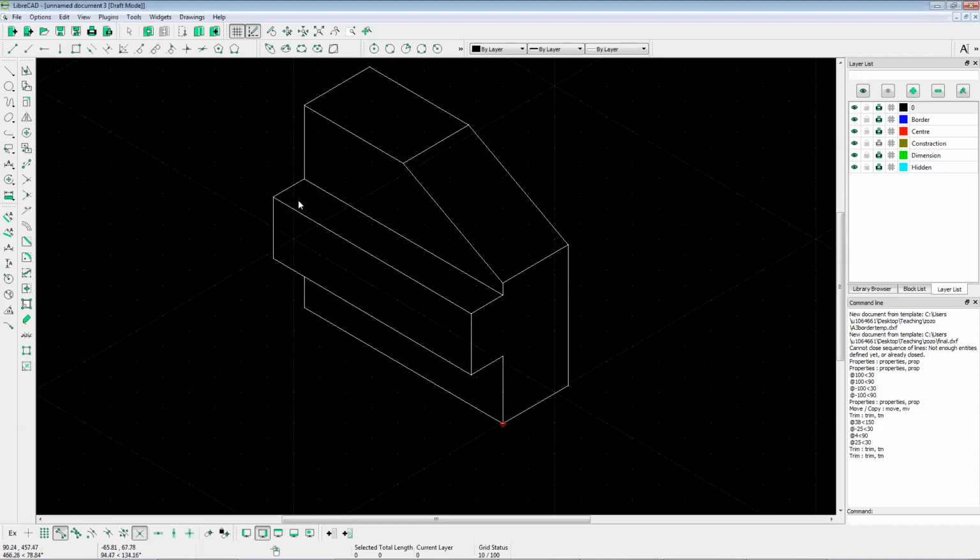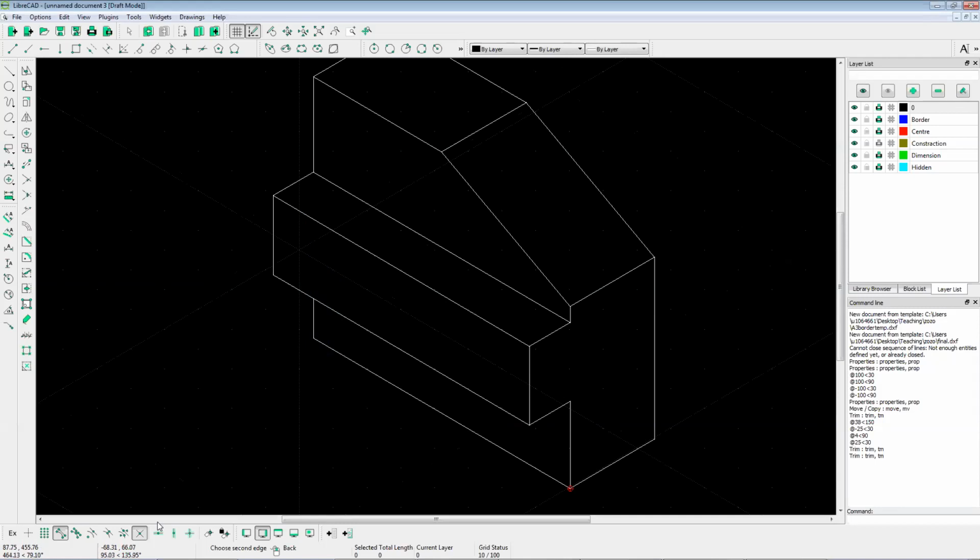So to do this, go to the snap tool, deactivate everything, and then choose snap middle, and grab a line from there. Select the line, and then go to specify the next point. So the line will go in this direction by 16, specified at 16.